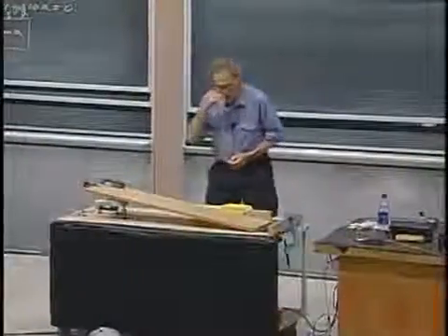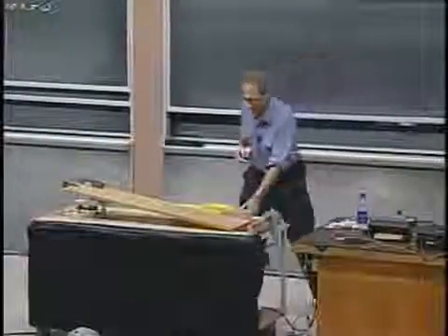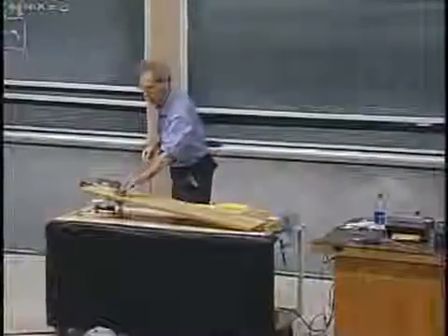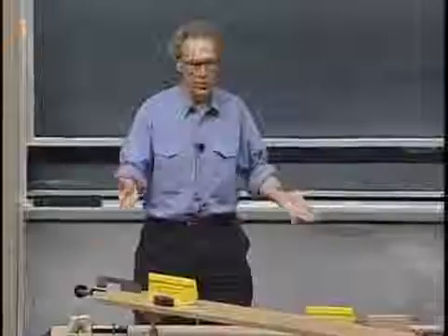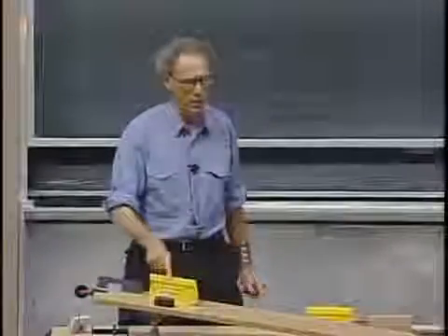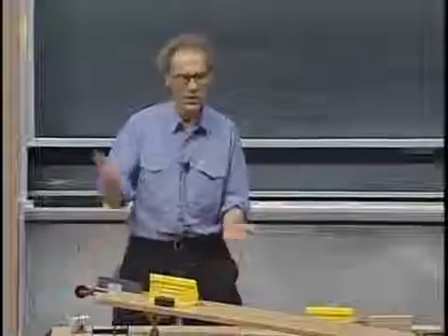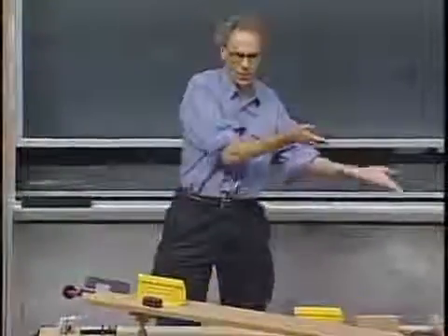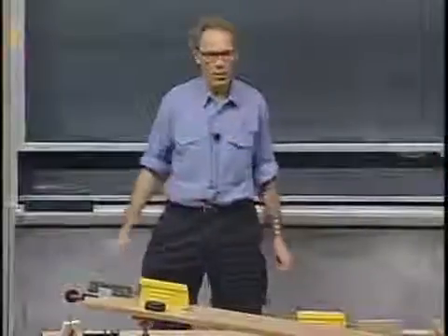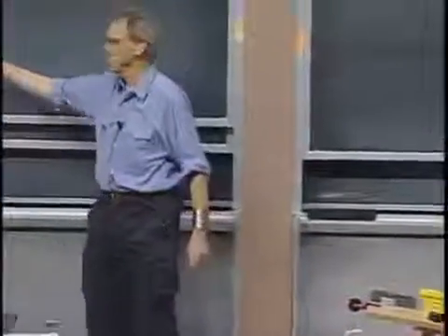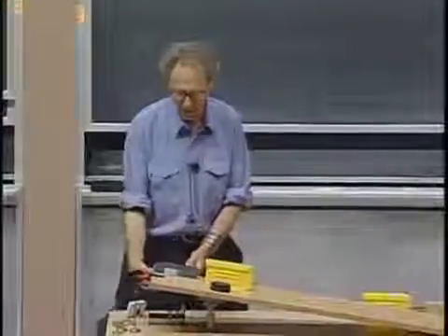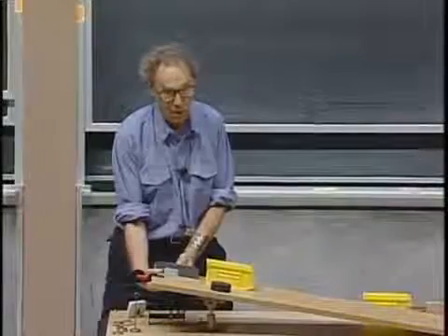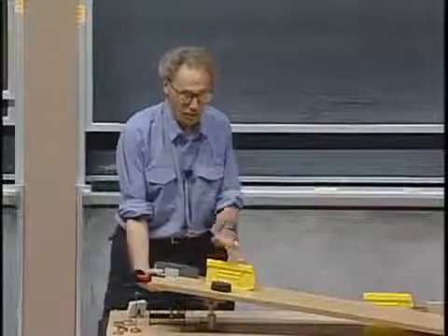The first thing I want to show you is if I take a rubber puck and I put it on this incline and I have a plastic bin, which is quite smooth, I put it on here, it's immediately intuitive that the friction coefficient of this plastic bin will be lower than of the rubber puck. So when I increase the angle, you expect that first the plastic bin will start to slide and then the rubber puck. And if I gave you the angles at which that happened, you could actually calculate the two values for the friction coefficient, which I will not do now, but I will do that later. So all I want you to see, I hope, is that this one will go earlier than that one.